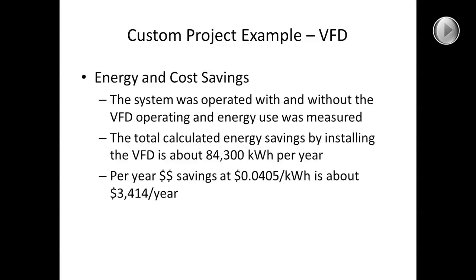With the installation of the pivots, we took measurements with the VFD running and without, and the total calculated energy savings for that project was 84,300 kilowatt hours per year. At their current rate at the time, cost of electricity, they'd save about $3,414 per year.